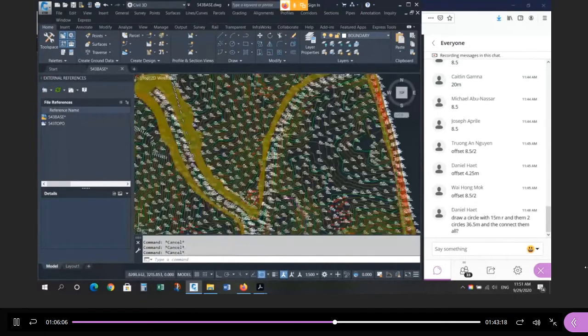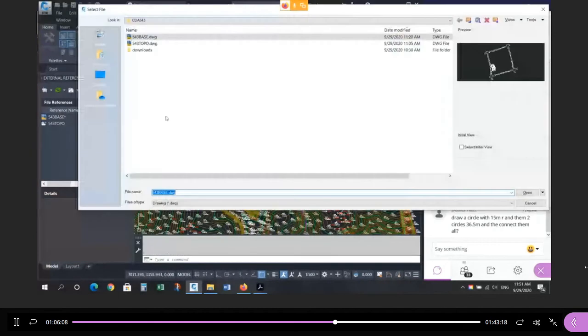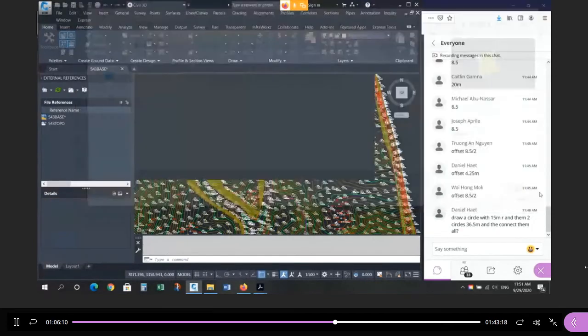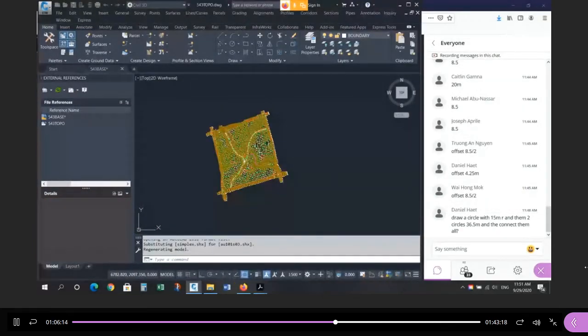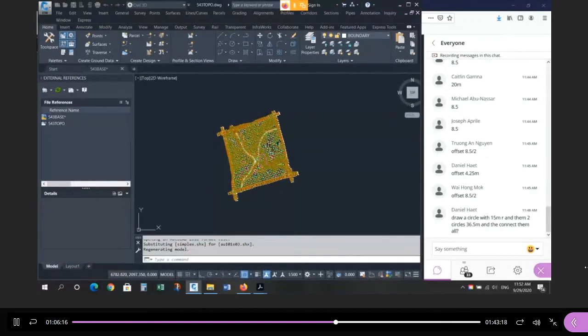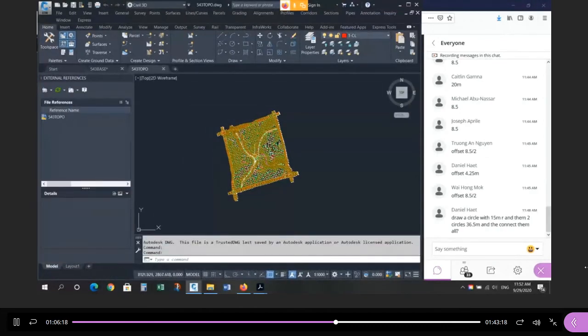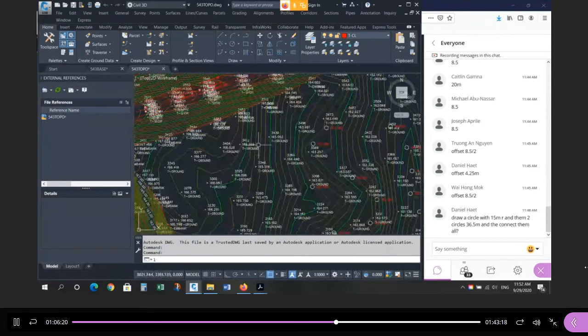It should be on the C10 layer. Let me just check that. Otherwise, it's not going to disappear, because you can't freeze layer 0 when you're working in a file. So let me just double check this. A little bit of housekeeping. We talked about this last day.